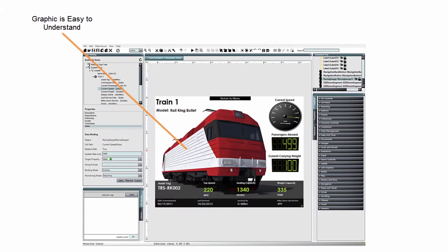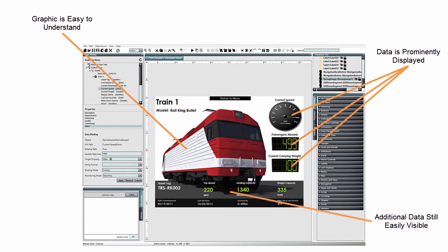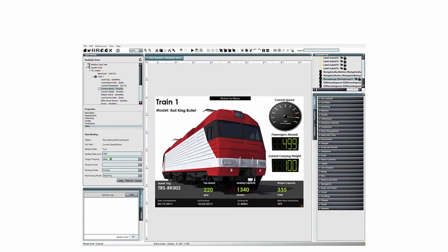One of the biggest challenges a designer faces in HMI design is not only making the screens look good, but be functionally sound as well. A good HMI system will consistently display data in a logical, hierarchical manner so that operators can effectively do their jobs. For example, let's take a look at this screen capture of a sample HMI we've created.